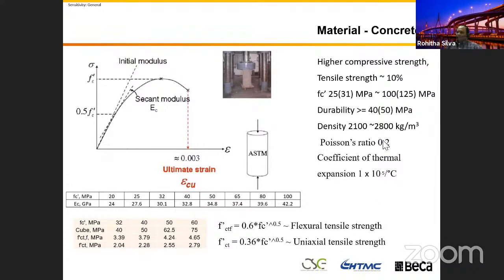Even for your structural modeling, the Poisson ratio is important. In addition to that, the concrete Young's modulus is important. I have this table, where Young's modulus varies for the various concrete types. If you use the British standard, you can calculate them.